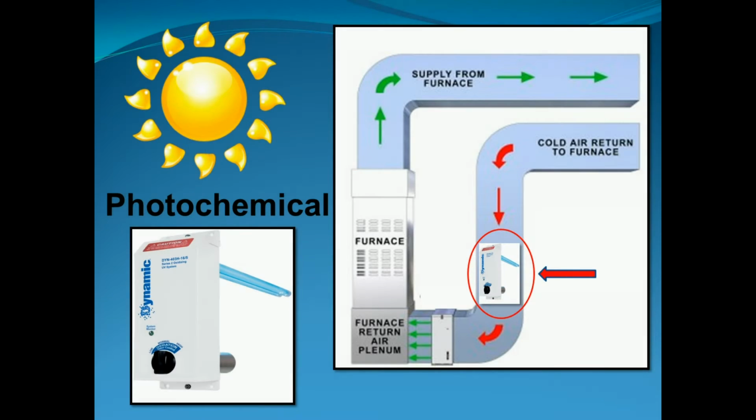Well, remember we've been talking about in many modules about how much air we move with an air handler. It's 3 to 5 times an hour, 96 times a day, 1.2 million cubic feet of air a day go through most air handlers. So let's use the air handler as our air moving system, which it is to heat and cool. We can heat now, we can cool, and we can treat the air. So instead of treating the air out in the breathing space, we're going to treat it inside of a chamber.